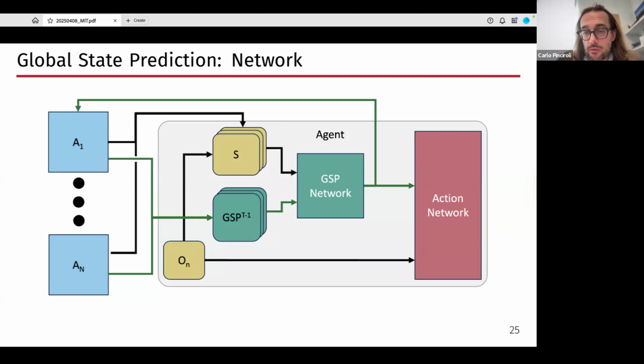And we want to minimize the amount of information that is shared. So what we do in this case, again, in the spirit of minimizing the information shared, we take the proximity sensors, we average them out, and basically every robot sends a vector form of this averaged out proximity sensing information.